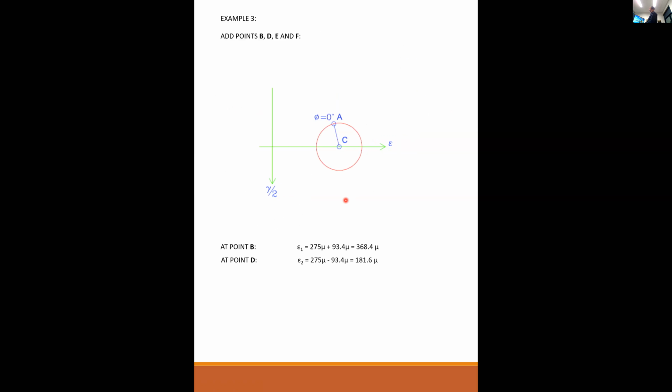And then we got those 4 points there. And then epsilon y on Mohr's circle is going to be 90 degrees away from epsilon x, which on the circle is 180 degrees. So a 90-degree transformation angle plotted at 2 theta or 180 on Mohr's circle. And I think that's good for tonight. So that's slide 197.